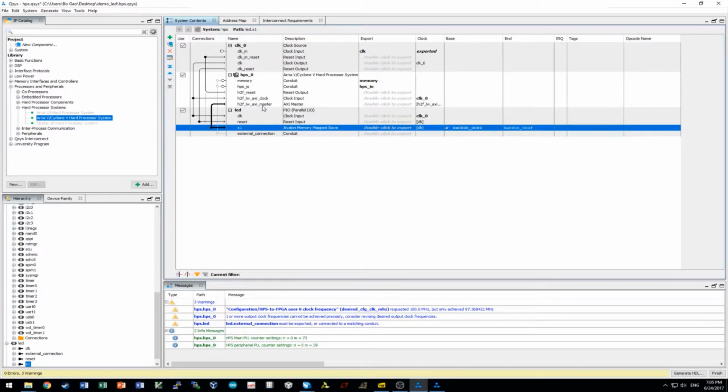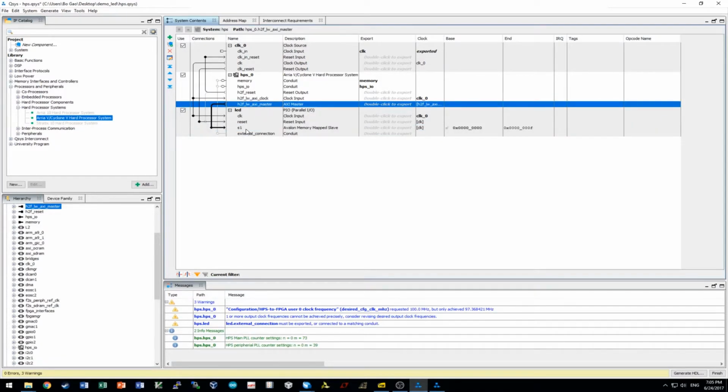So you see, this is an AXI bus, and this is the Avalon memory map bus. So in between there should be a pipeline Avalon bus memory map bridge, and you can explicitly add them, or you can just leave it there, and when you're compiling the Qsys project, Qsys will automatically insert whatever bridge converters are going to be needed. So I will just leave it this way.